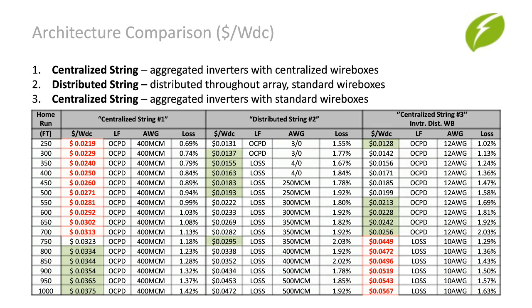What this is telling us is using the external DC combiner does not pay off for us until we reach an 800-foot home run distance. If you're using a 2 megawatt building block, that is 16 of the 125 kilowatt inverters and 16 combiners, depending on the architecture you chose.